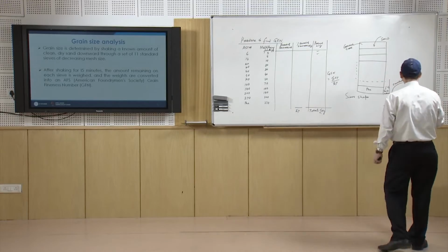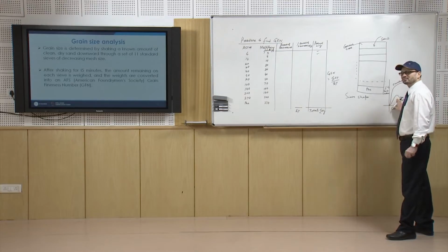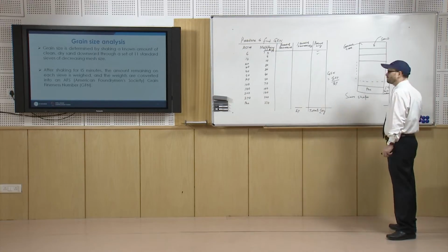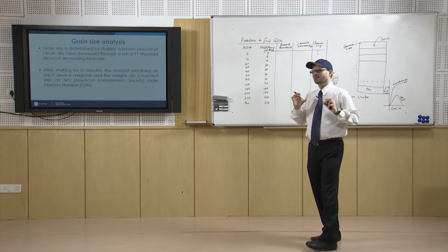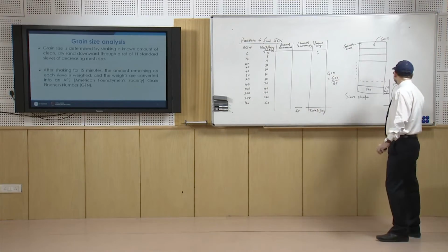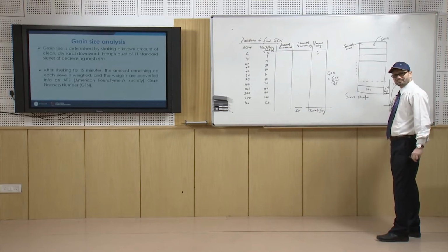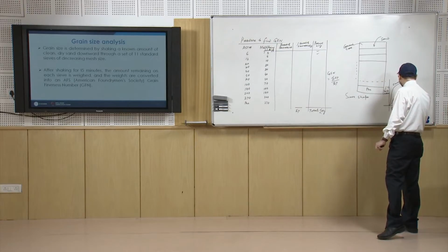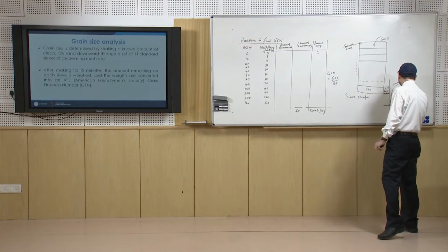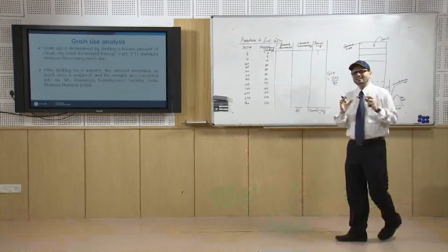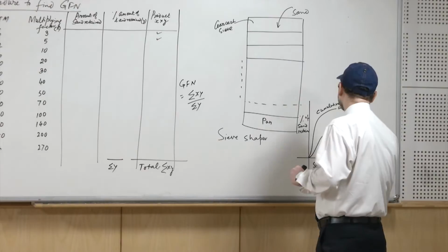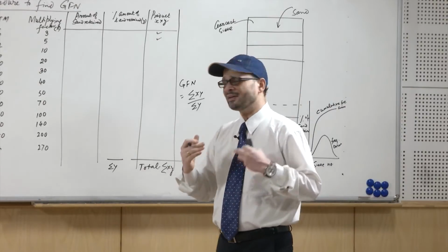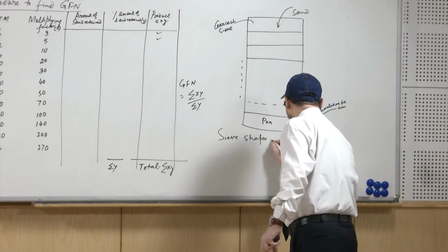Now, what is the significance of such a curve? This curve shows one peak. So, this is basically typically a type of normal distribution curve with a single peak. This tells that mostly the average grain size is here, and you have some of the sand lesser than that and some more than that, but they are in smaller quantities.